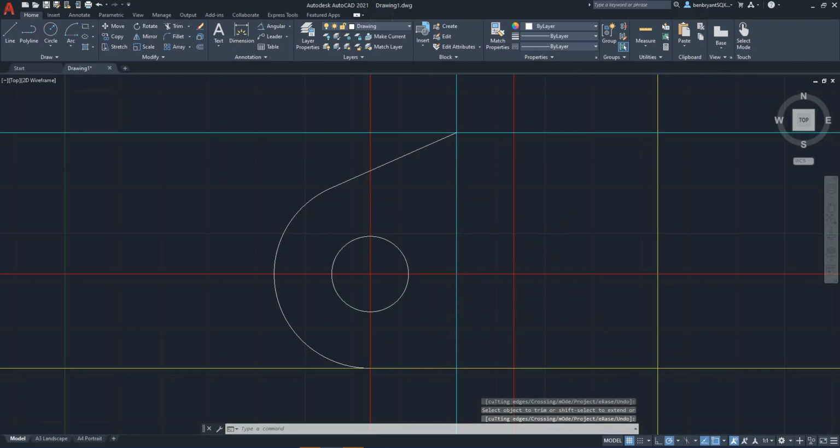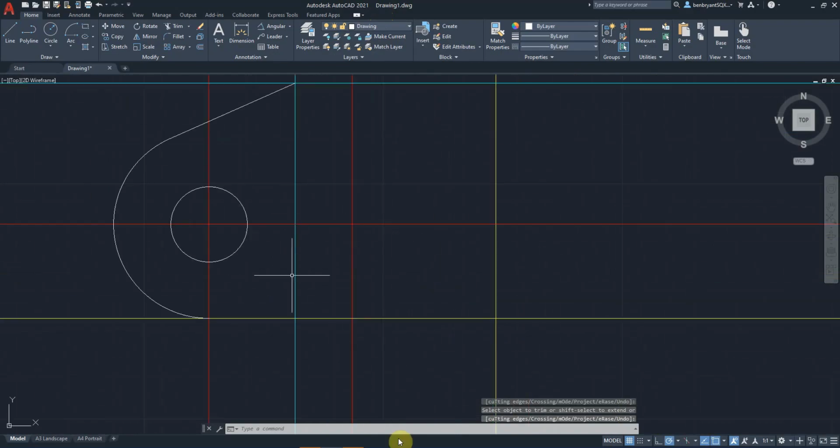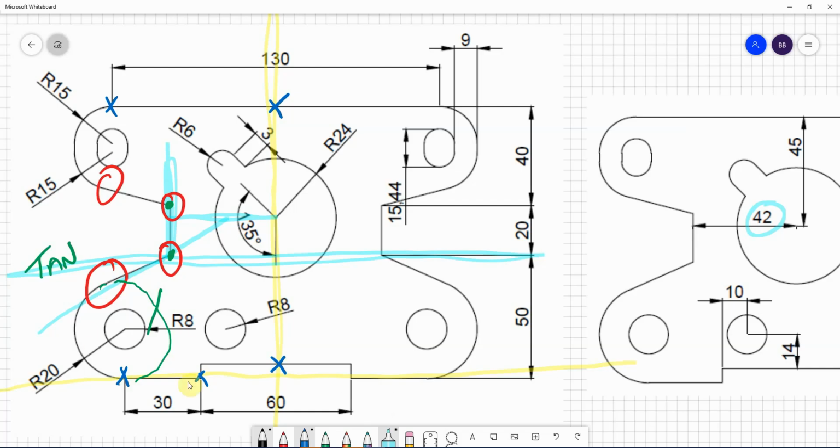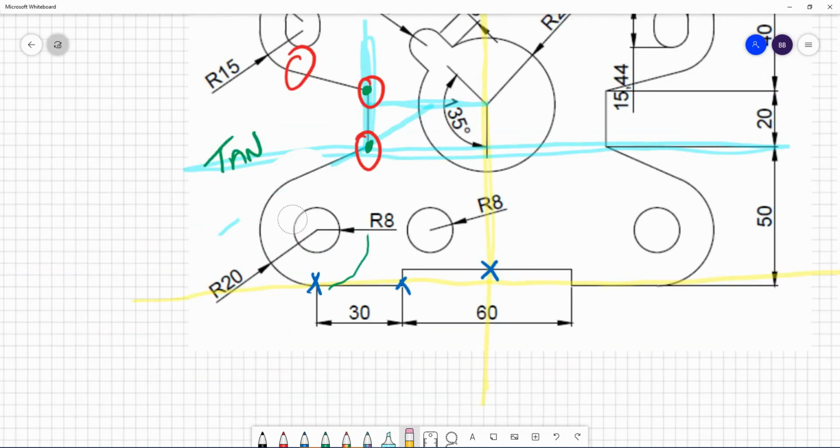Like so. So that's now my first arc feature, which is down here. Okay, so now we put our tangent in, and we're going to work on our next part. What I now need to do is put this step feature in here, so that when I mirror this component across, I've got those full features involved.